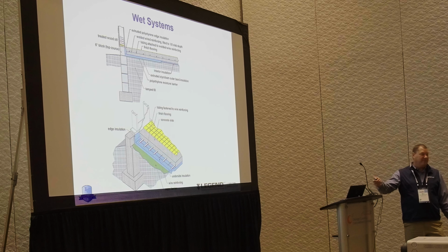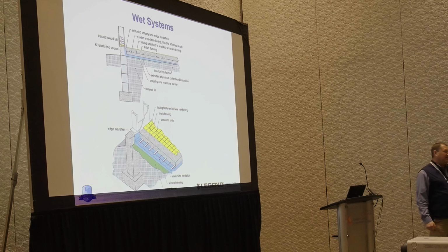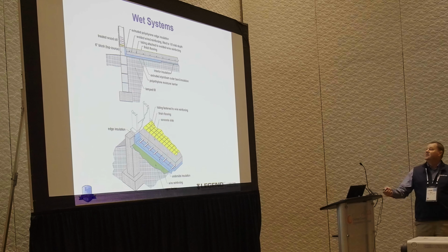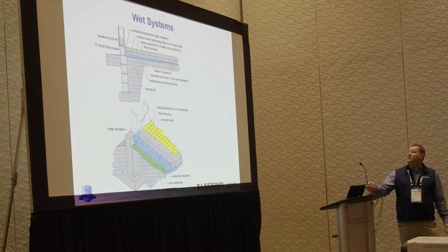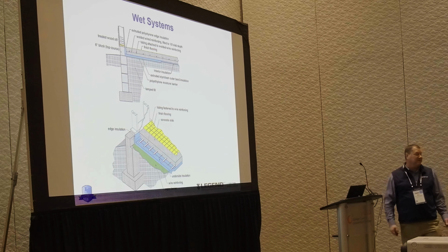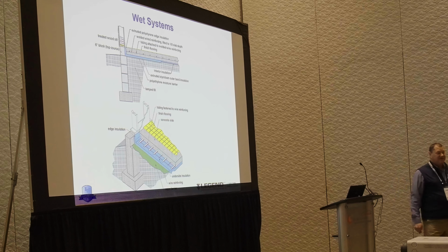They had a 4-inch slab pushing up against the footings. It's bleeding energy, and you get a green ring around the house in the middle of the winter because it's keeping the soil at about 50 degrees and the grass keeps growing. Tulips popping up in February. Yeah, so that's a big deal. You forget to do that, you can have an issue with it. Forget to put insulation underneath it completely, you can have even more of an issue.